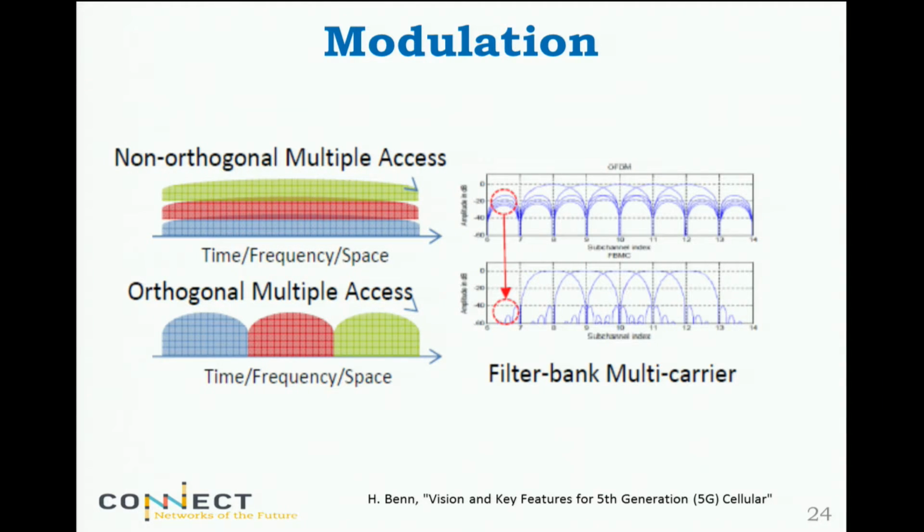There is also something to do with the signal structure, how you play with guard times, what we call the cyclic prefix in OFDM. They try to either minimize the use of guard times or remove them altogether, to enable short delays. You want to process things faster in some applications in 5G, and OFDM is not too good for that.